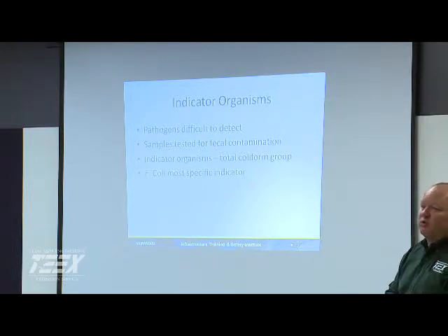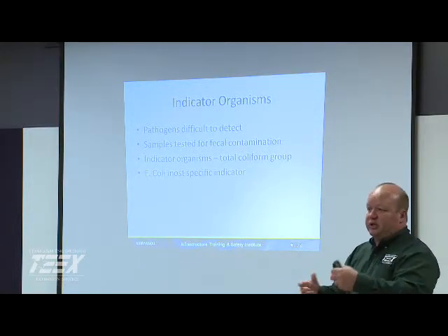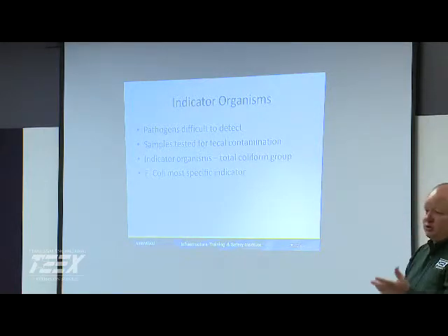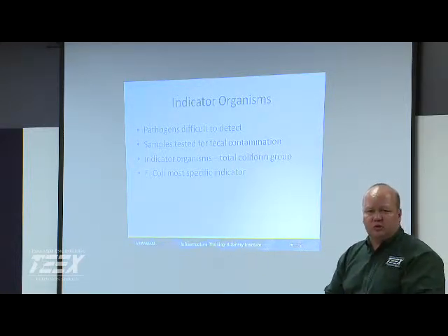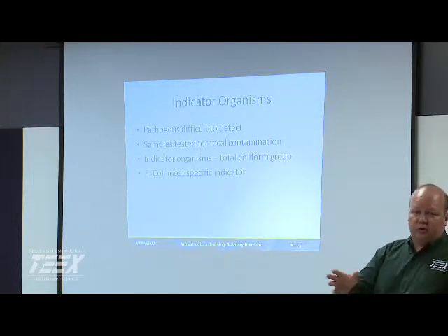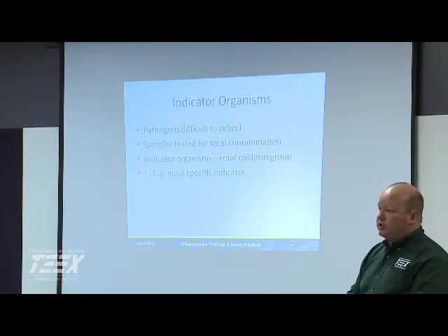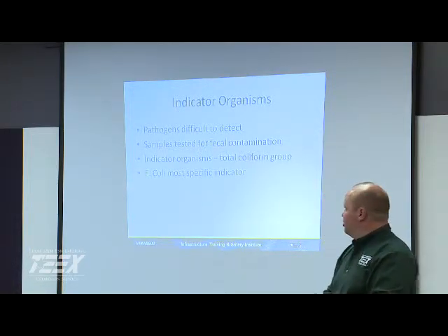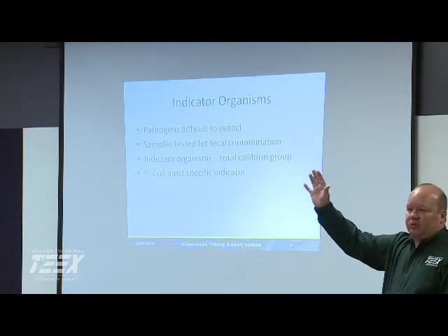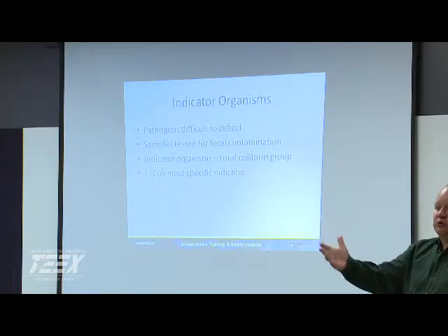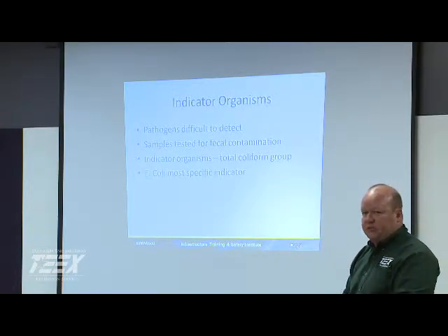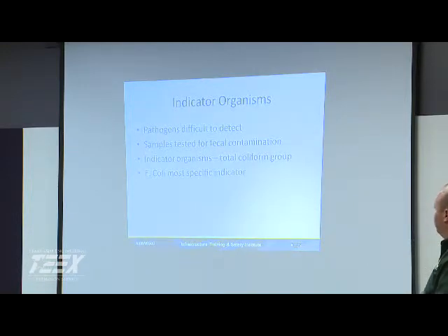The source water, knowing what's in your water, what's in your watershed, is a big impact on what's coming into your intakes. And wellhead protection, for those that are doing groundwater, y'all have small groundwater systems there that y'all are using? Okay, so you got a well pump. Wellhead protection is huge, critical. Abandoned wells is a big issue. Having those out there in the system that are out in the middle of a field somewhere somebody had 50, 60, 100 years ago. Nobody knows about it, and it's an open source of contamination into your aquifer.